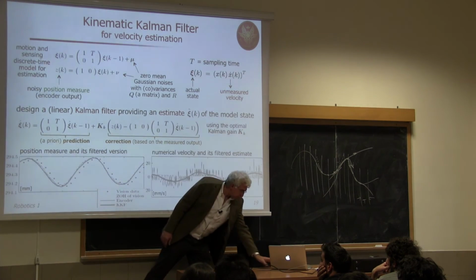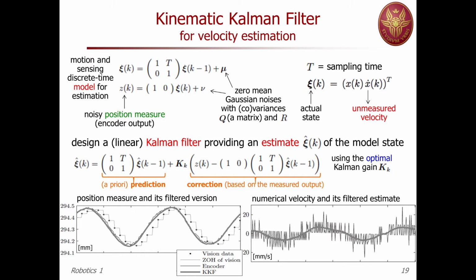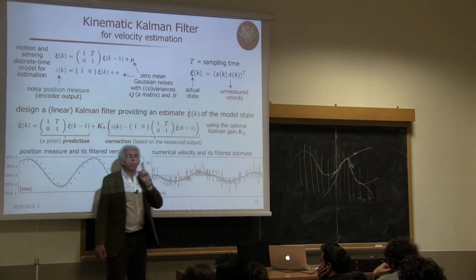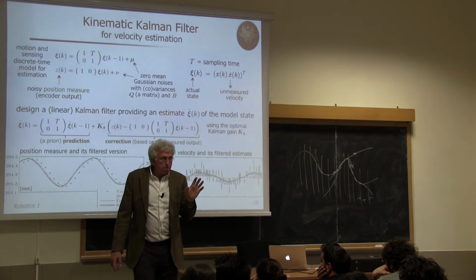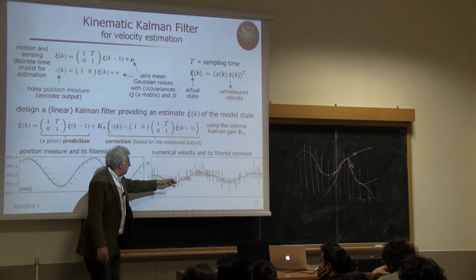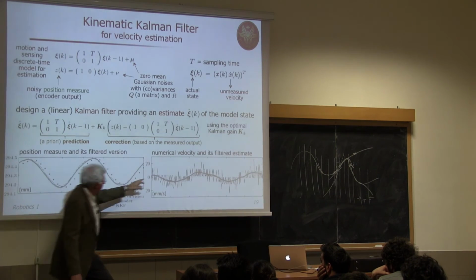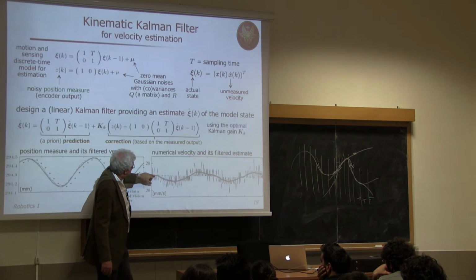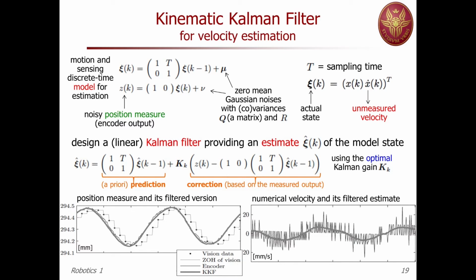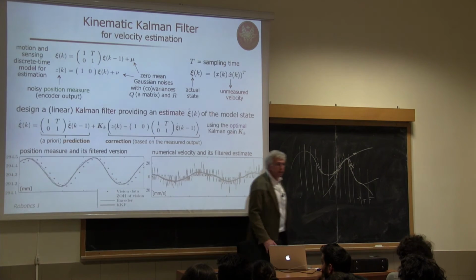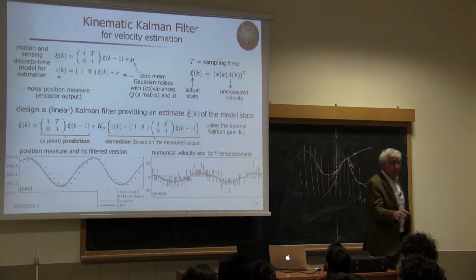So for instance, here you have a typical situation where these spiky signals are the measurements, not filtered by the Kalman process. So out of this you take some signals like that, and as second component of the filter, you have also this estimate of velocity. Okay? You see that you can remove quite a lot of noise from your data with these techniques. Of course, it's more computationally intensive because this is right at the core of your measurement system.